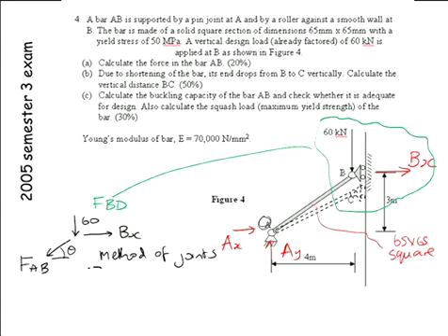So you would look at forces in the y direction equal to 0, and from that you would solve for FAB, and the force in FAB will work out to be minus. And what does that minus sign mean? It means it's in compression.